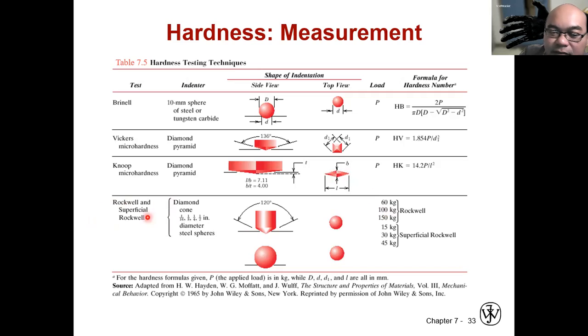Then we have Rockwell and superficial Rockwell, using a diamond cone. This is the load as we mentioned earlier: 60 kilogram, 100 kilogram, and 150 kilogram.